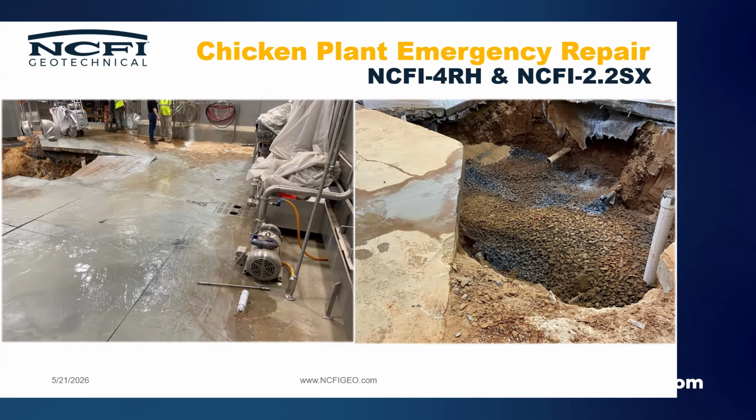Various rooms had different types of equipment in them. In one room we had a big oven. In one room we had this big freezer. This freezer is on your right here. That thing's built in place, and there's no way of working around it. Where they didn't have equipment, they wanted to go ahead and replace all these floor drains and all the plumbing. Of that 60 feet, the original trench that was dug for these utilities was probably only about 35 or 40 feet of it in width. They did a horrible job of recompacting that and installing the plumbing. That's where the failure was.